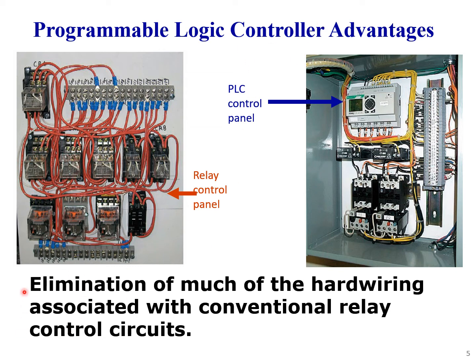What is the main advantage? Elimination of much of the hard wiring associated with conventional relay control circuits. You see that we have lots of hard wiring here, and all of these wirings and relays are replaced with this PLC. The rest of the circuit has nothing to do with the logical circuit, and this whole circuit is now basically compacted into the PLC.